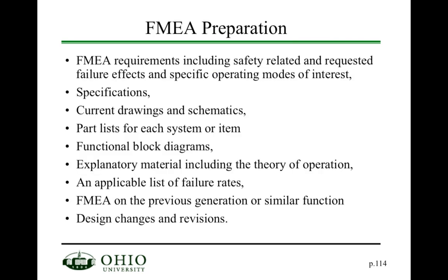So in preparation, of course, we want to have all the information, so all the specifications of the system, the drawings, the schematics, the list of parts, any functional block diagrams that indicate how particular functions or components are related, and any additional material that explains how it works, how it operates, and of course the list of failure rates of all these components.